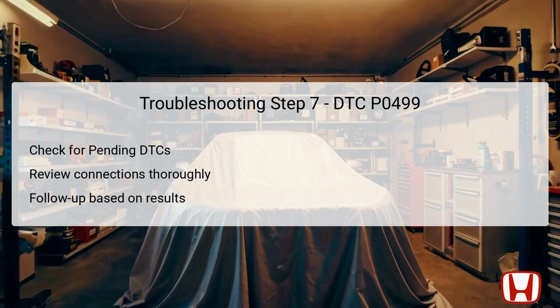A thorough visual inspection of wiring and connectors can often yield insights into ongoing connectivity issues. If previously made changes to the ECM/PCM have not effectively cleared the DTC, it may be prudent to either substitute a known good component or revert back to Step 1 for further investigations. Maintaining a systematic approach to identifying problems is essential for effective troubleshooting.